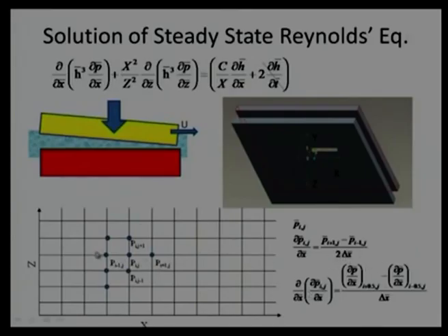And if we go for the second gradient, in that case we are required to calculate p at the mid node, that means somewhere here in between, and the pressure gradient at the mid node. But the mid node will not be there when we implement this formula over here. It will be only the nodes. So, that is some sort of accuracy requirement we arrange.